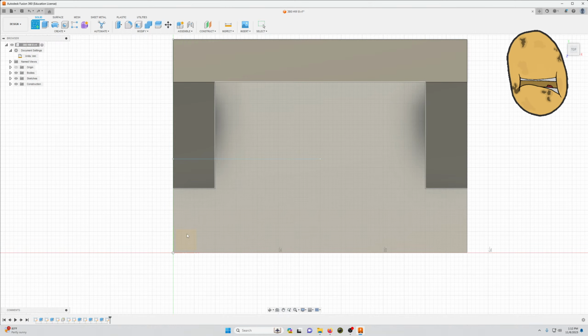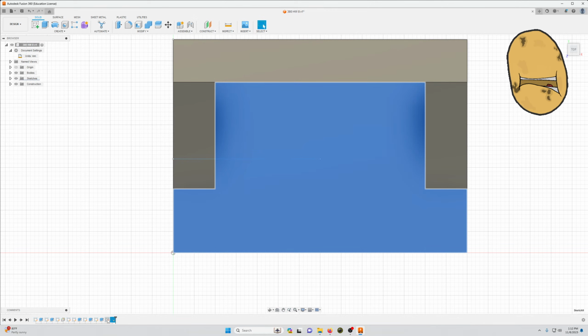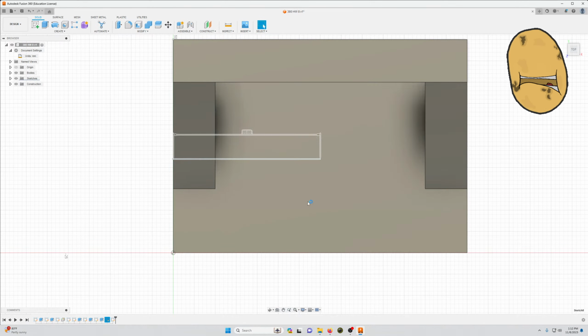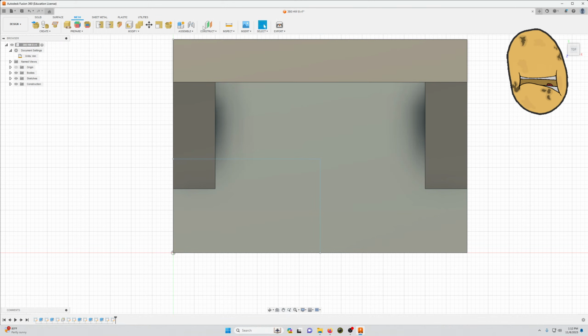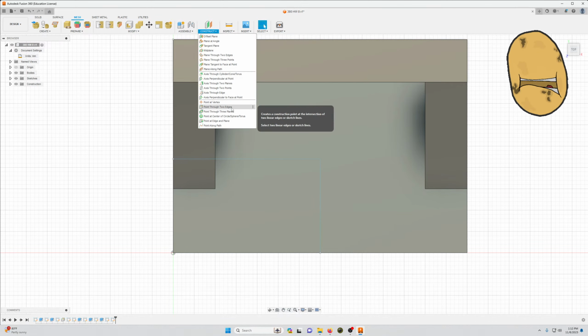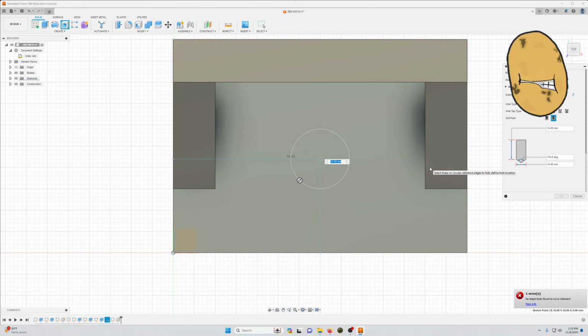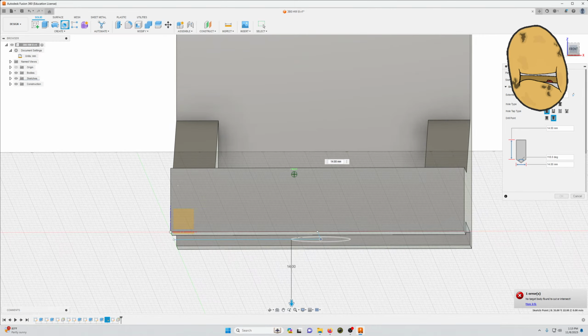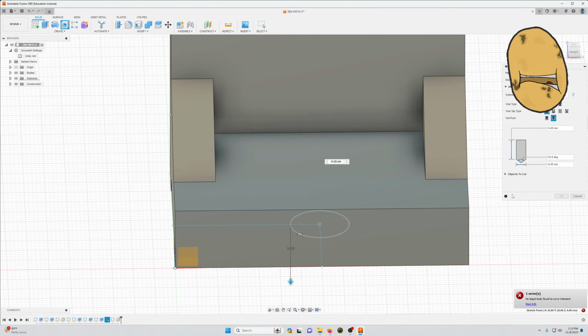Let me go to sketch. Actually, let me just go to edit sketch. Hold on. This is sketch, right? Oh, go ahead and edit the sketch. Create another line here. Goes all the way to the bottom. And then let's see if we can do that other option now. The point through 2 edges. This guy and this guy. Yes. Point there. Let's see if we can create a hole now. Okay, that works. It created it at the bottom, but that's fine.